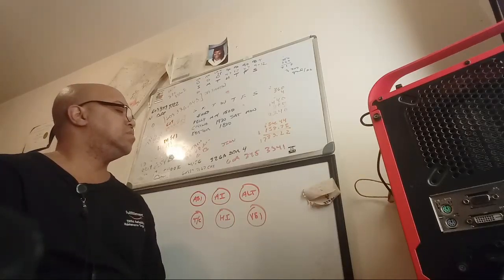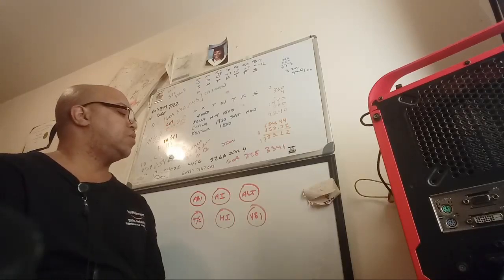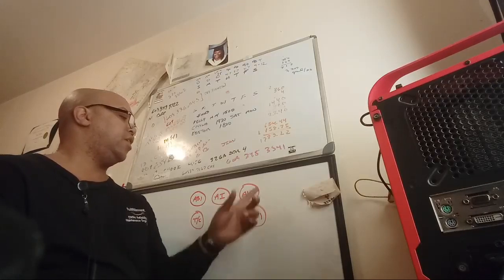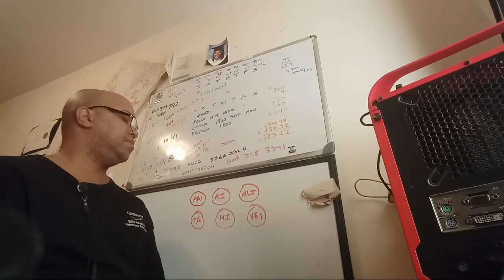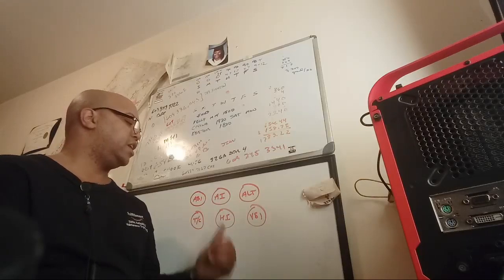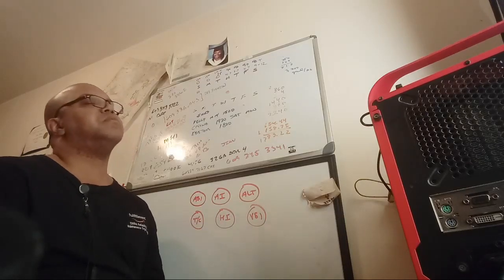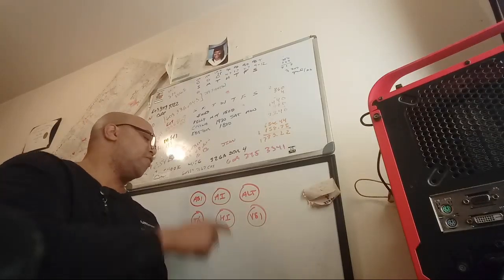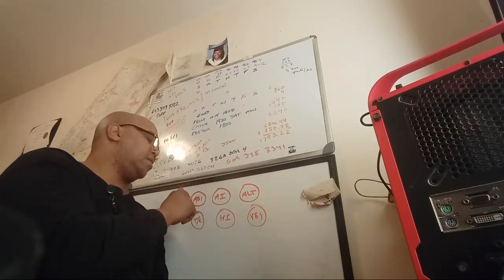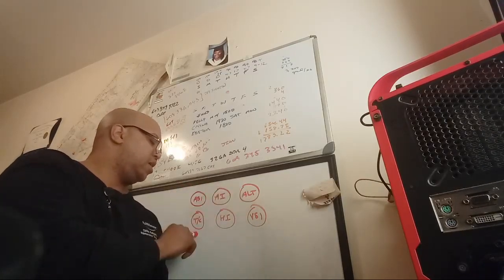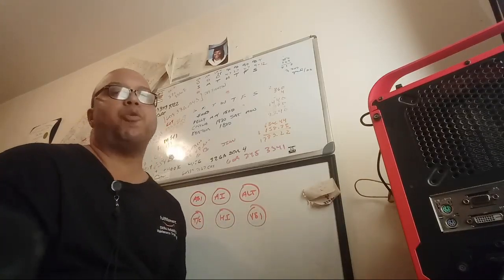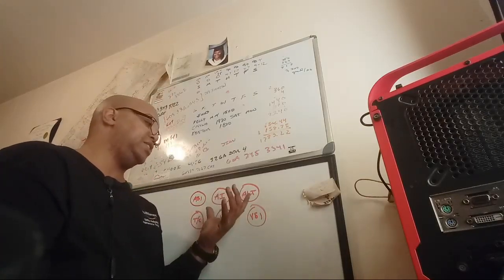You have your vertical speed indicator. That's down here. You have your altimeter. Your altimeter's up there. Very good. You have your heading indicator, bottom center. Your turn coordinator. So from left to right and top and bottom: airspeed indicator, attitude indicator, altimeter, turn coordinator, heading indicator, and vertical speed indicator.